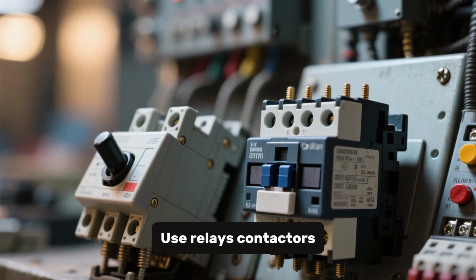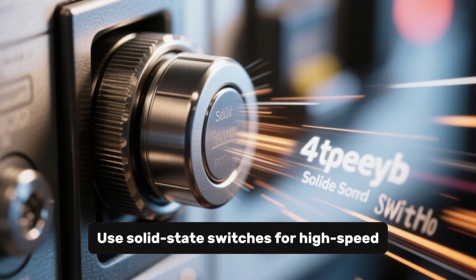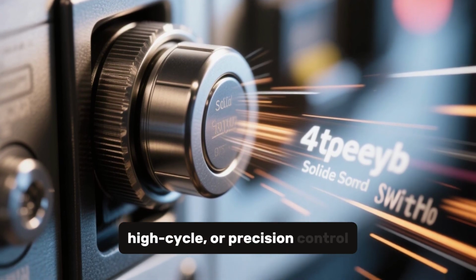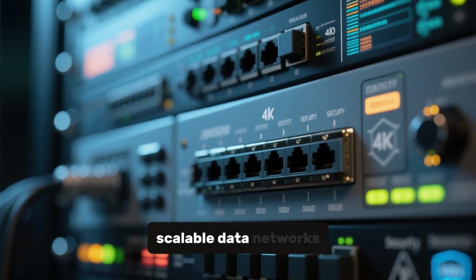Use relays and contactors for remote control of high-power loads. Use solid-state switches for high-speed, high-cycle, or precision control. Use managed network switches for secure, scalable data networks.